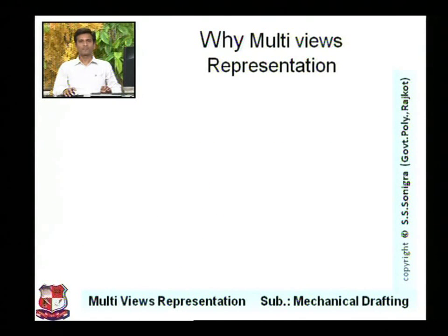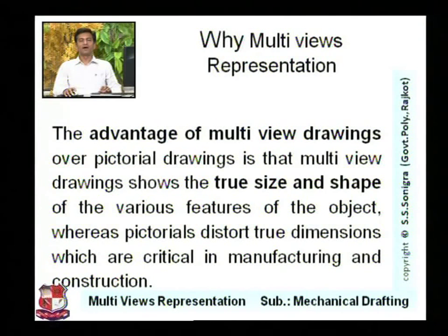Why multi-views representation? What's the importance and why is it used in drawing practice? The advantage of multi-view drawings over pictorial drawings is that multi-view drawings show the true size and shape of the various features of an object, whereas pictorial views distort true dimensions, which are critical in manufacturing and construction.